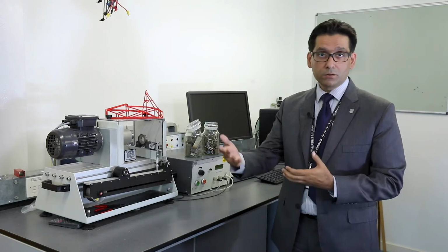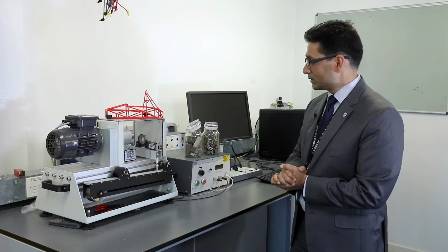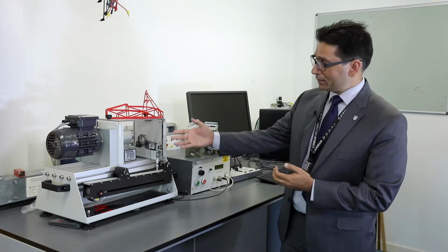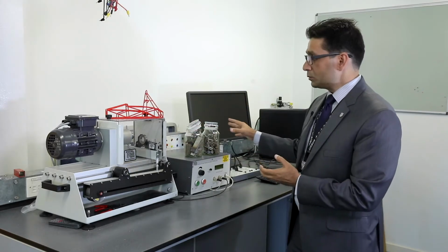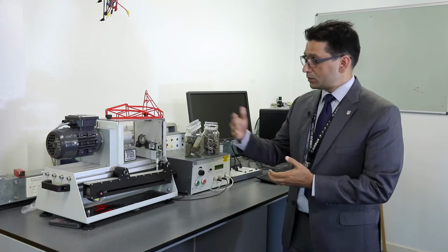This is our general engineering flexible laboratory, we call it. Here we have our fatigue testing machine. As we understand, fatigue is about cyclic loading, about vibrations. So this is another key asset that we have in engineering. The principle is pretty straightforward. Our students machine these samples in our general engineering workshop, and once they achieve the correct geometry, they place it in this machine. It is connected to a computer which is capturing the data, and that's how they understand the fatigue properties of materials.